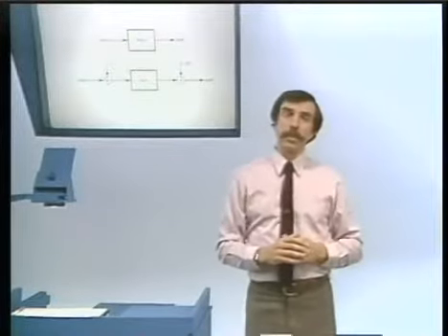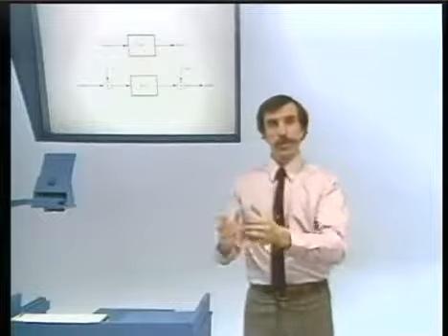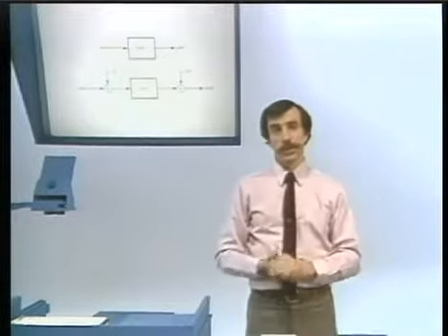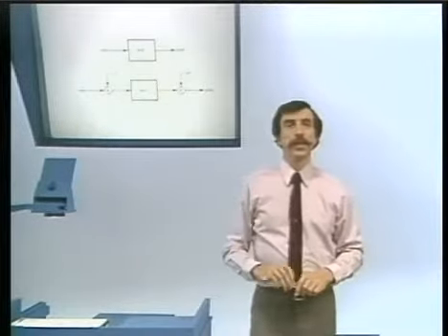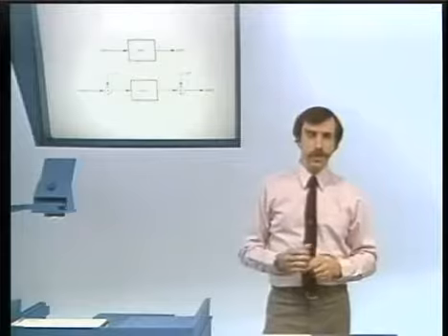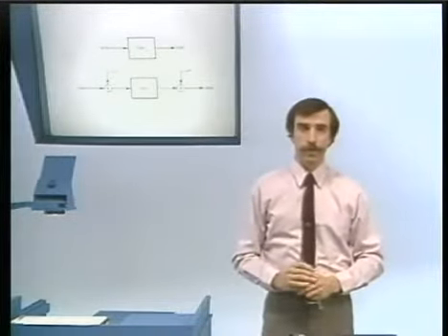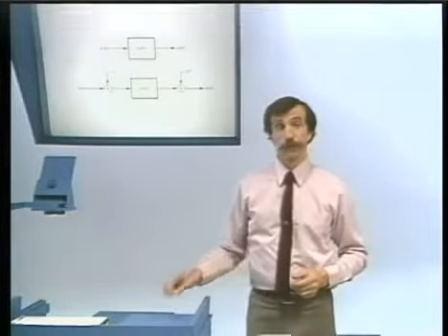The example that we happened to pick said if you modulate by -1 to the n, that takes low frequencies and shifts them to high frequencies. What that tells us as a practical and useful notion is the following. Suppose we have a system that we know is a good low-pass filter. How might we use it as a high-pass filter?